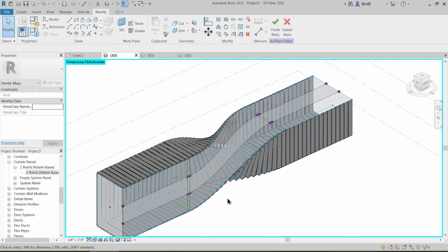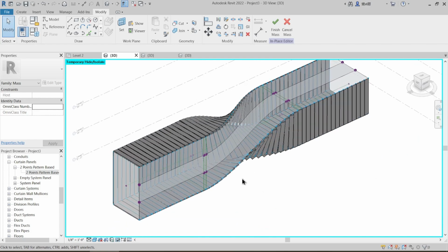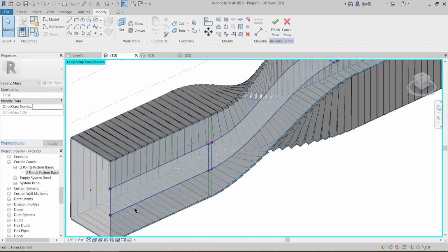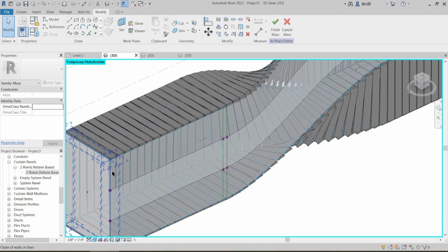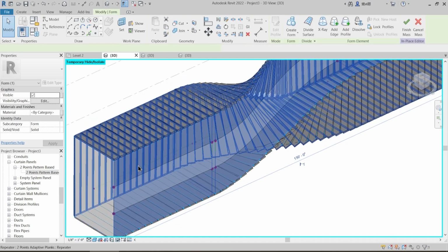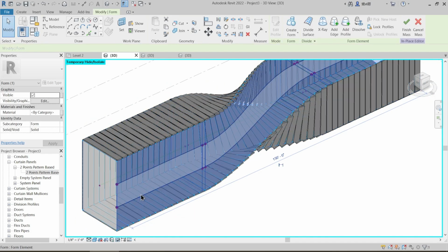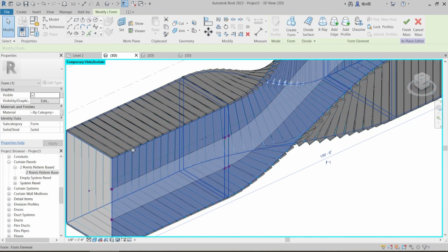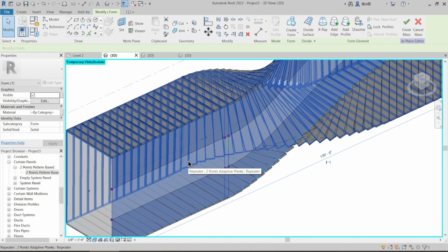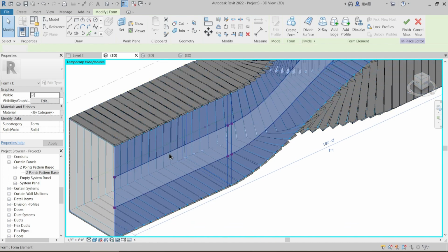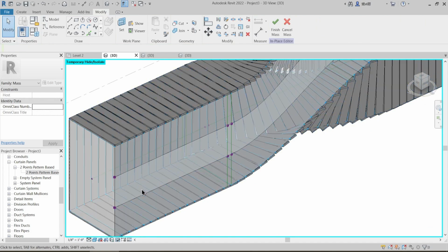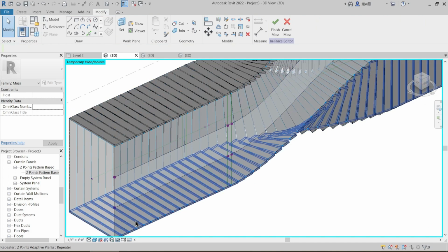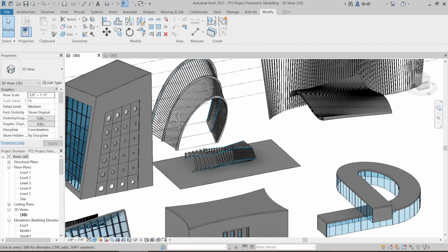Okay, so now we can manipulate it differently. But before that, we also need to create the upper 2 segments, because if I ever go to select this whole surface, then it will select that whole surface and will manipulate it that way. If I ever try to lay the planks or glass or mullions or whatever, then it will manipulate it the same way. So just like we created the surface, we need the 1 and 2 as well.